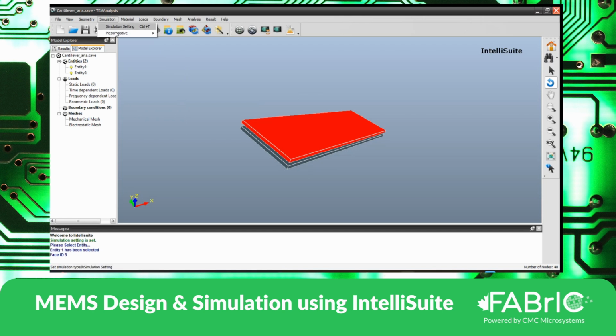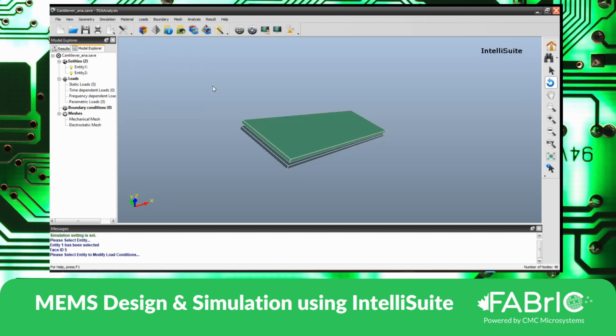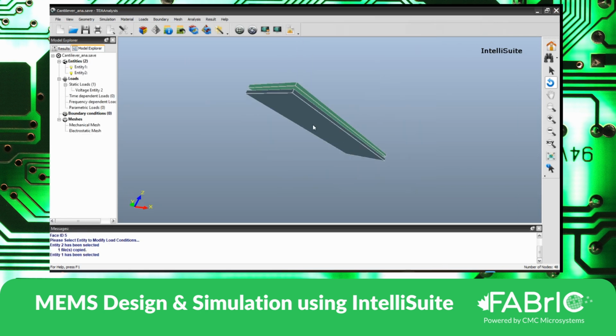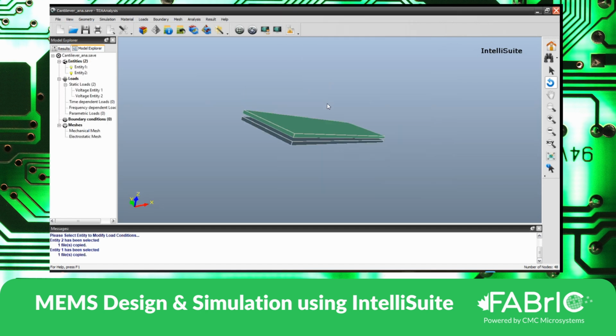So now the simulation settings and materials are done. Loads: what is the type of load? We are trying to simulate the deformation due to electrostatic force. So I apply 30 volts to this and 0 volts to this.